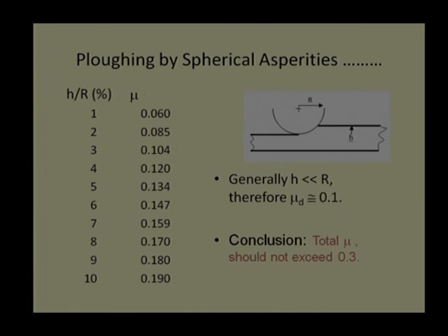So, even in this case if we say that few asperities are conical, few asperities are spherical, I will get some intermediate value. After running-in time, all conical asperities will be damaged and will turn out to be some sort of spherical asperities, and I may get intermediate results. But that still is not going to give us the satisfactory results which we showed earlier as an experimental result, the coefficient of friction being very high, say 1, 2 and 3. That has not been explained with these theories. That means, these theories have some shortcoming. These are classical theories. We need to explore some new theory.